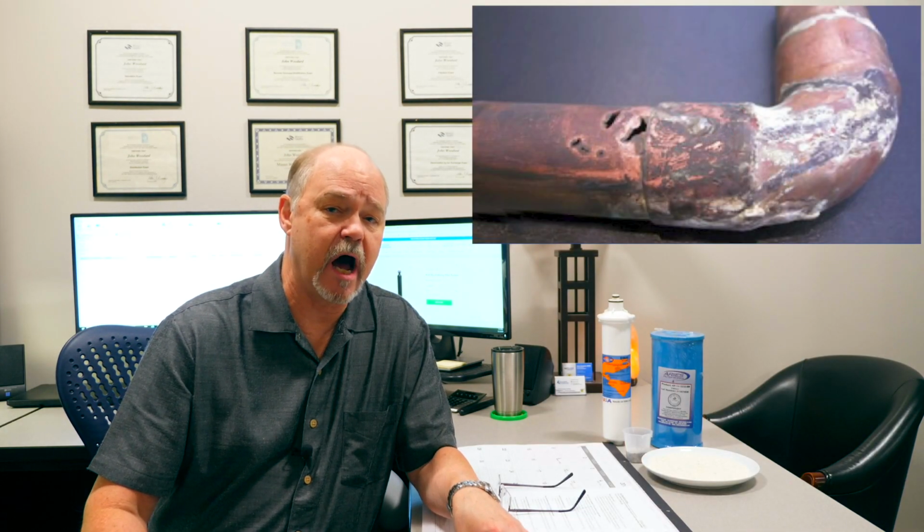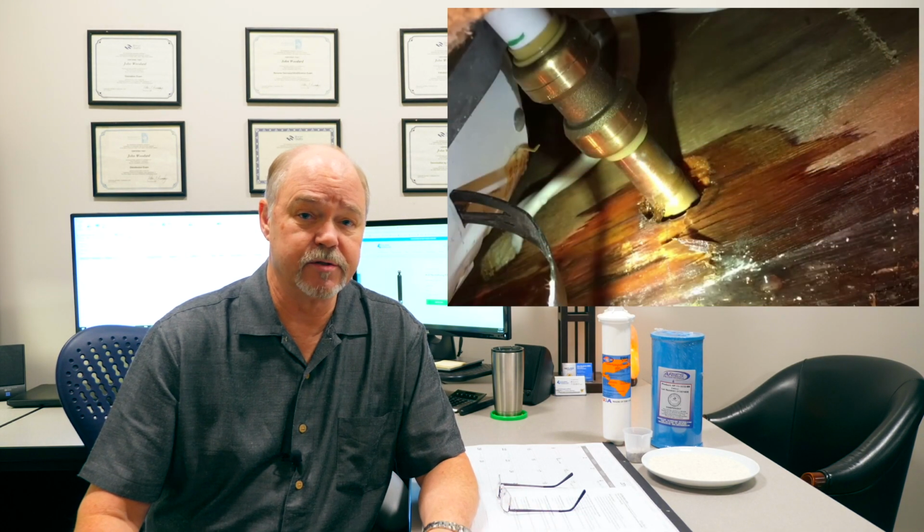By golly, if you have acidic water, you want to treat the whole house because that acid water is destroying all your plumbing. If you are seeing blue or greeny stains on your drains, that's what you've got going on. You've got acidic water that's actually eroding the copper from the inside of your plumbing. And if that's left unaddressed, what happens next is you'll get pinhole leaks. And you know Murphy's Law, those pinhole leaks are going to be behind a wall someplace and you're going to have lots of damage to repair.